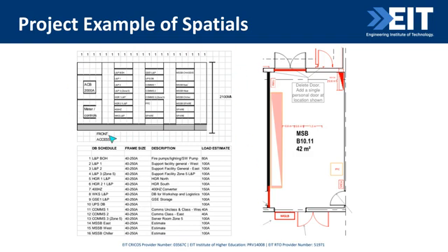Here's another example of the same tool, but with obviously 1, 2, 3, 4 cable zones, incoming breaker, and 3 tiers of outgoing supplies. So this project, we followed these 4 steps that we went through before. How many outgoing boards is it supplying, from light and power through to communications or mechanical? How big we think those supplies could be.